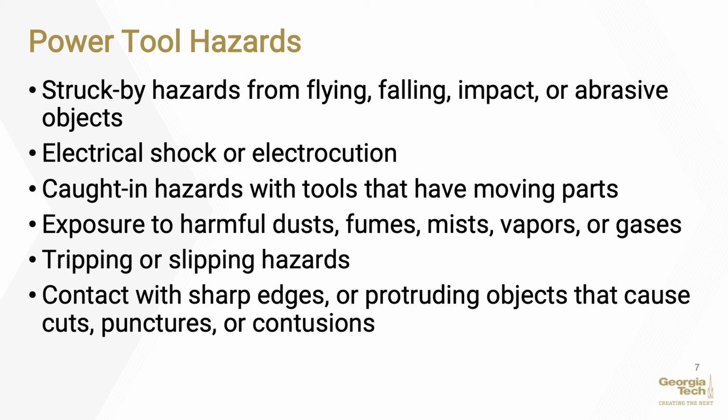Never yank the cord or the hose to disconnect it from the receptacle. Keep cords and hoses away from heat, oil, and sharp edges. Disconnect tools when not using them, before servicing and cleaning them, and when changing accessories such as blades, bits, and cutters. Keep all people not involved with the work at a safe distance from the work area. Remove all damaged portable electric tools from use and tag them "Do Not Use."